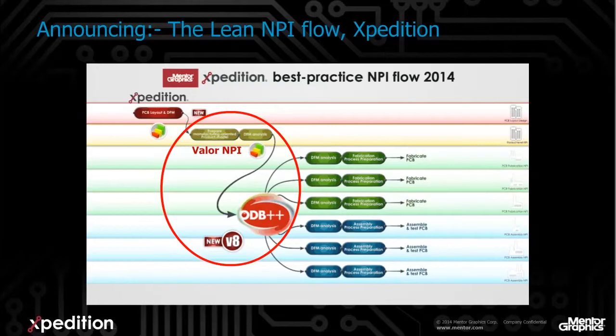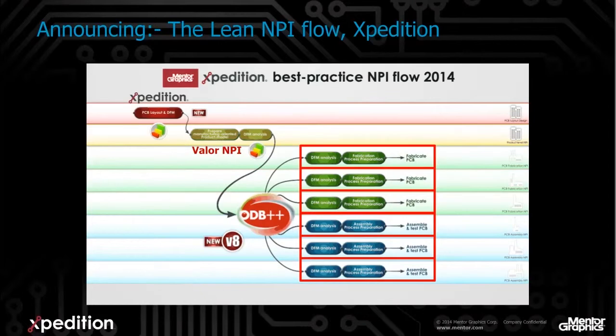The second aspect of Lean NPI is the use of intelligent, integrated product model data for handoff to the process NPI stage. By preparing a single product model that is DFM validated and does not require reintegration by the manufacturers, a range of benefits are achieved in the NPI stage, including time savings in both product and process NPI stages, a reduction in the risk of mistakes and misunderstandings, and higher consistency of product across multiple manufacturing suppliers.